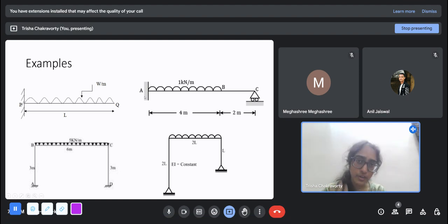So you will get some warning time in case the structure is about to collapse. If the support reactions or anything fail one by one, you will get warning time to evacuate and all that. And if the duration of the earthquake is short, the structure may not collapse, because a few modes fail, but the other modes are enough to keep the structure stable. Then you will of course go for repair later on. But of course, the first step is not to make the structure collapse at once, because if one failure makes a structure collapse, it is too unsafe.